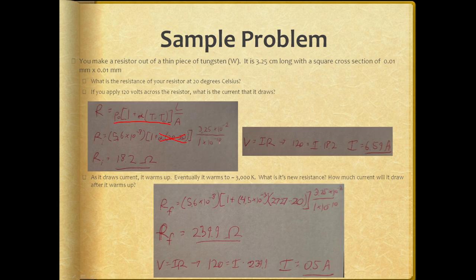In this particular section of the class, it's important to keep track of what units of length you're using, because most wires, most resistors tend to be really small. Their surface areas tend to be really small. Occasionally their length is really small. Like the commercial resistors that I showed you in lab the other week are very, very tiny. They physically don't have a lot of length inside of them. So sample questions, homework questions might often give you lengths in centimeters, lengths in millimeters. Make sure to convert them before you use them in the formula.